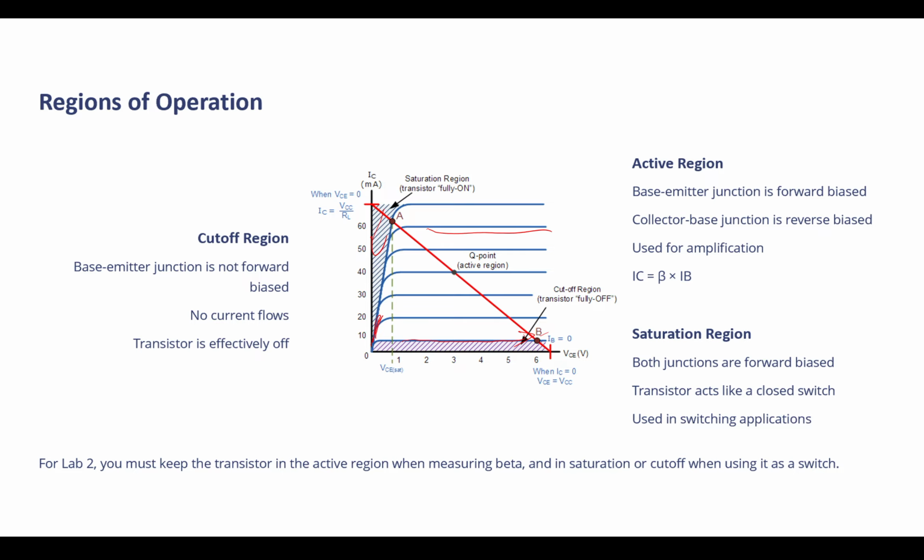And the part where the current gets saturated, we call the active region. Okay? So just try to note those so you don't get confused. The naming is different between the MOSFET and BJT.